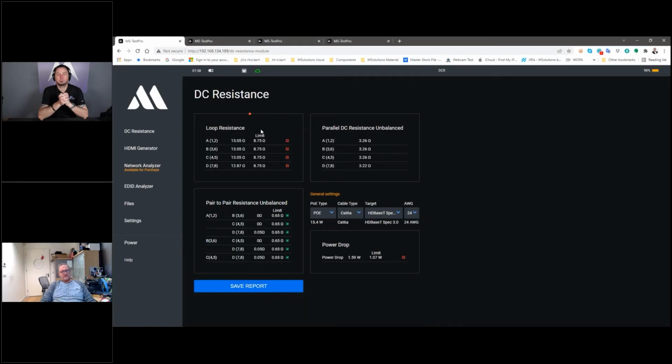It affects, as I said, the propagation of the signal through the line, and it also affects the power delivery from one side to the other. It is important, by the way, for PoE and POC. POC is not out of the loop with those numbers, and I'll tell you why. Let's say that you have a low current and it is the same all the time. It's a fixed current going through the line.